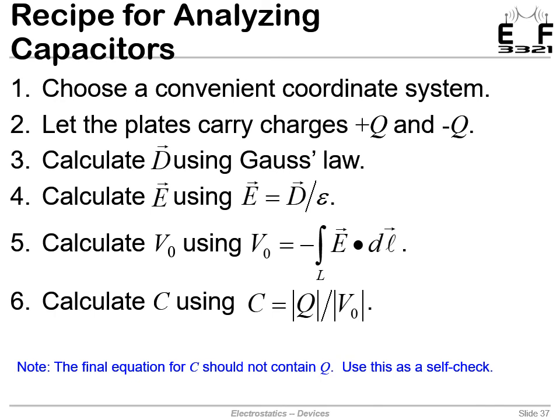Once the electric field intensity is known, then we can calculate the voltage between the plates by doing a line integral from plate to plate. Now we have the charge and the voltage. We're now in a position to calculate capacitance, and we'll ignore the signs here because capacitance is always positive. So we get some tangled piece of metal, we assume a charge, calculate the fields around that, do a line integral from plate to plate to get the voltage, and then charge over voltage is our capacitance.